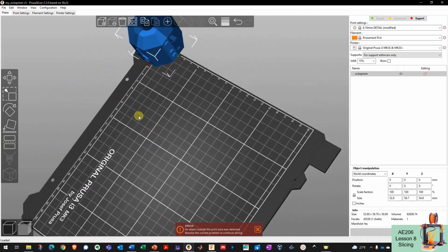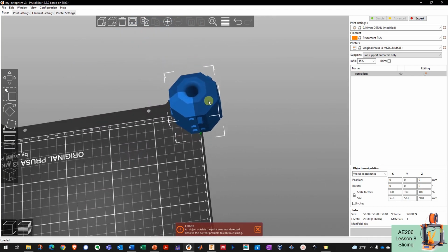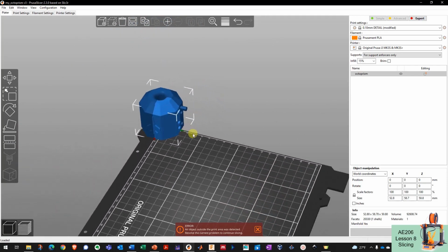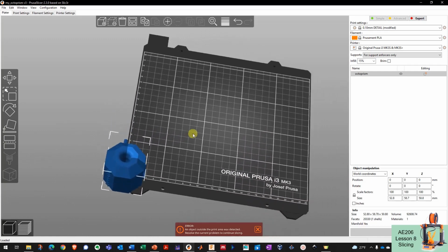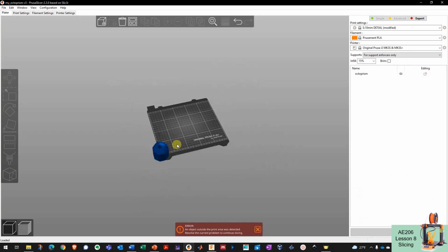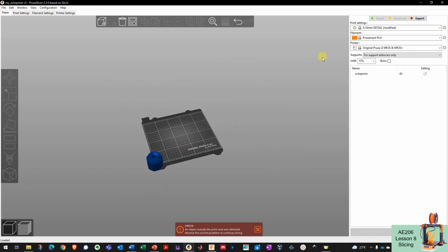And when I look over here, I see this dark blue color showing the part of the octoprism that's outside the print area, and the light blue is inside the print area. This is a really important point, okay? When you guys make your airplanes in Project 4 in Aero 206 and you import them in PrusaSlicer, sometimes they might show up way off in the distance over here, and that's because your model in Fusion 360 is not at the origin of the coordinate system in Fusion 360.